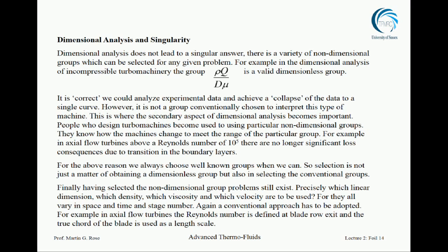Now, if I quote to you a Reynolds number in an exam question, I will say where the velocity is taken, at blade row exit or inlet, depending whether it's a compressor or a turbine. But you've got to be aware that with no definition, you can't use it. There's nothing singular about a Reynolds number until you know how it's defined.